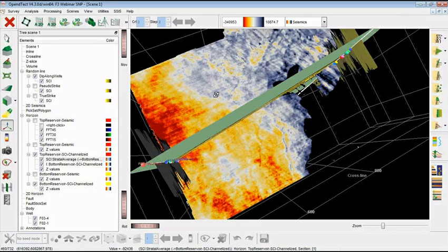You can make velocity models in OpendTect in different ways. You can use the Horizon Cube model maker and interpolate from wells. You can take the velocity model builder. You can import velocity models for migration. In all cases, you can use them. The scenes to create a new depth scene and convert your horizons to depth and create a gross reservoir there.